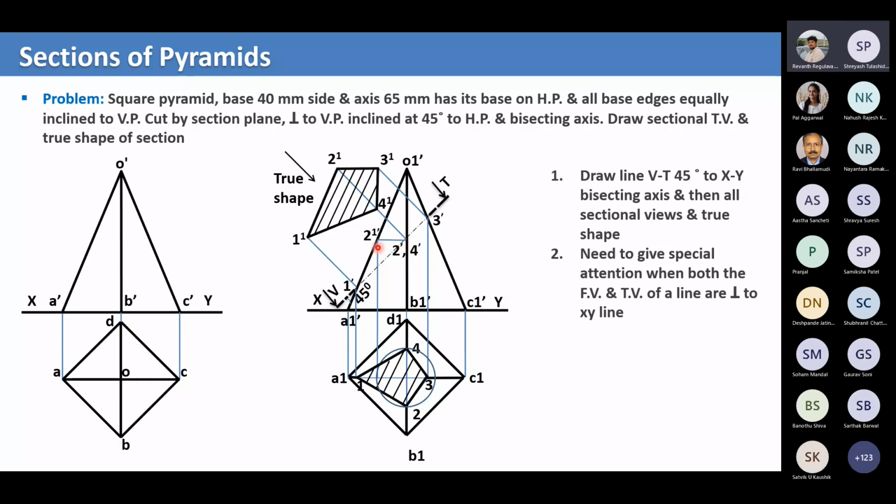Draw the horizontal. Now see, you just label this point with respect to this, to 1 dash. And we draw a vertical projector. And then taking this as the radius, O1 2 1. So this is 2 1 dash, so this will be 2 1. O1 2 1. And cut the arc above and below. Now this will be our top view of the cross section. Everyone get it?